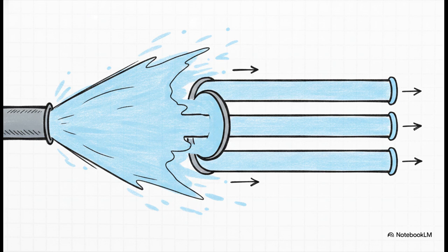When you actually run that inverse equation for our three 85-ohm bulbs, boom! Our total resistance drops dramatically to just 28.57 ohms. That's way lower than the 85 ohms of any single bulb. And because that overall resistance is so much lower, the current can flow much more freely. So while each individual bulb draws about 0.565 amps, the total current leaving the battery is the sum of all three. That gives us 1.70 amps flowing through the entire system. But hold on.